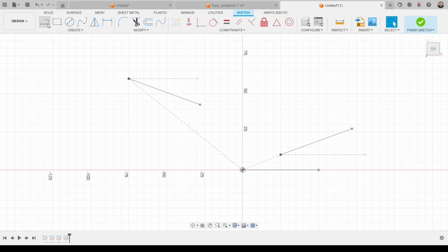So that's why I will create the lines centered and perpendicular, but going in the upward direction. And these symbols are telling me that I am creating those lines correctly. I need both the perpendicular and the middle symbols. Okay, so now I can trim these parts of the lines away, and I have found the origin for link number 2. So that's one part.